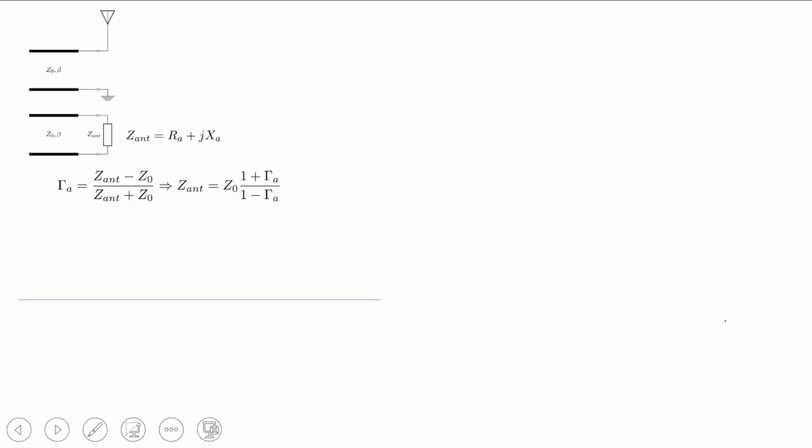Gain is one parameter of an antenna, but we are going to look into the other parameters that describe the performance of an antenna. What we saw earlier is that when we have a guided transmission line with a characteristic impedance Z0, the antenna is a transducer that converts the guided transmission into wireless, unguided transmission.